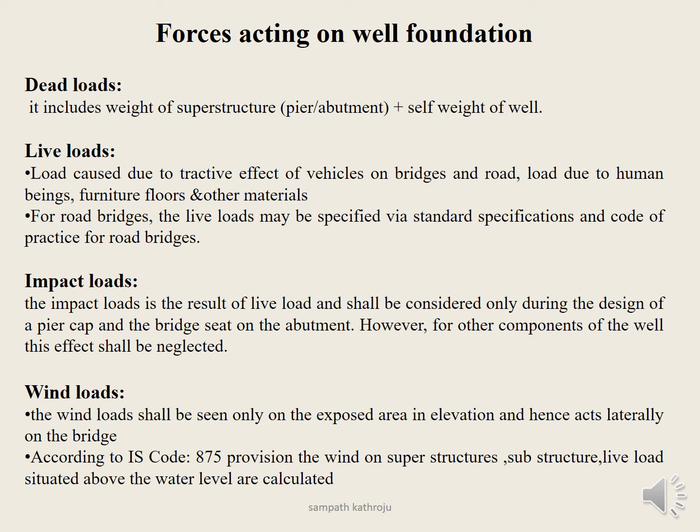Impact load. The impact load is the result of live load and shall be considered only during design of the pier cap and the bridge seat on the abutment. We have seen the seat on which the pier was in the previous figure. So in the bridge seat designing and designing of the pier cap, these impact loads are taken into account. In other components, this impact load is neglected.